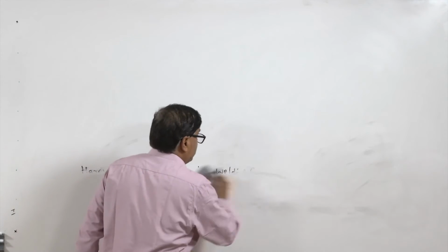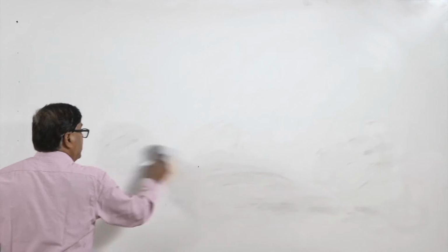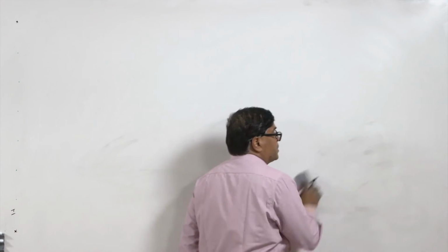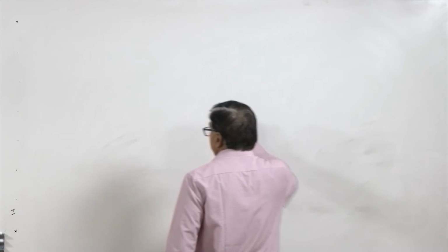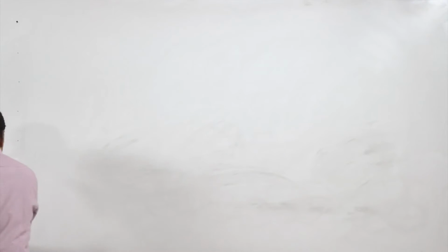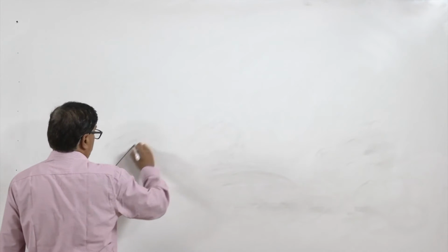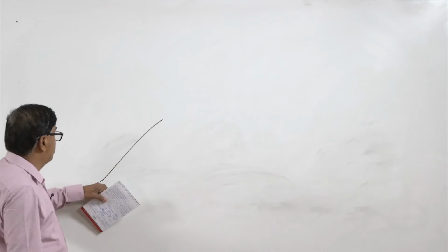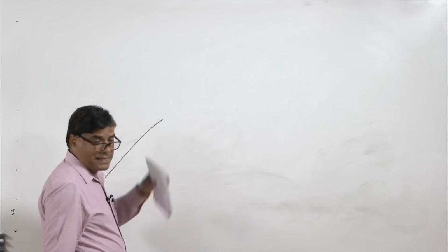And what is that? The welding current value is increased gradually, and it is also reduced gradually after the welding time. This is called slope up, the rate at which the welding current value is increased from 0 to the desired set value.